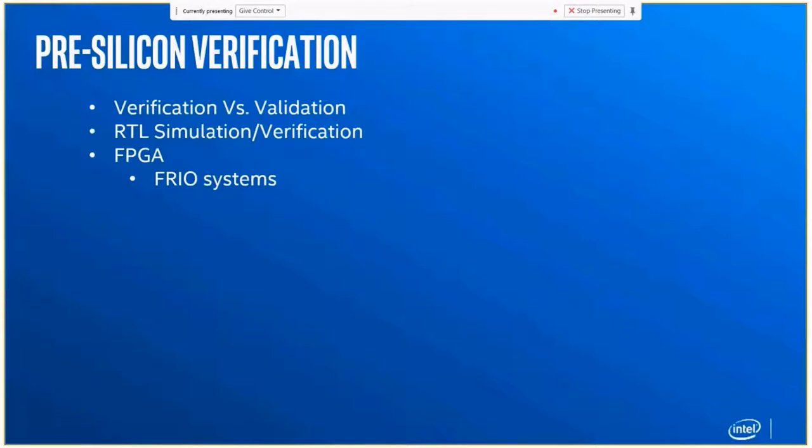So in this stage, there are these huge FPGA boards that have a bunch of FPGAs put in, and then you take the entire chip, like Snow Ridge, Lionfish, whatever, and you take the same RTL, literally individual clock, bit, byte, rise, fall, register, the entire design. You pour that into the FPGA, so you get a small section of the chip simulated here, right?